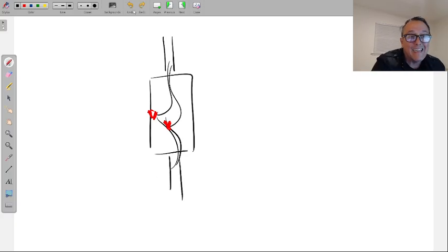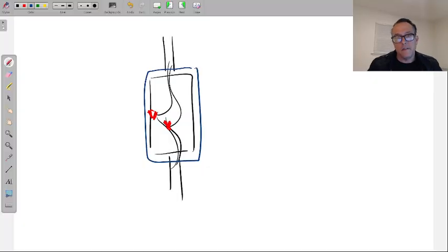Unfortunately, instead, you're supposed to put a blank cover, like the one I showed you in metal, but if it's on the drywall, they're usually plastic and white or whatever color the other outlets are. You might have seen these before. They get screwed into the box, blanked over. Now, the only thing is you have this blank cover on the wall, and some people don't like it. It's aesthetics, which is why they might just bury it behind drywall.